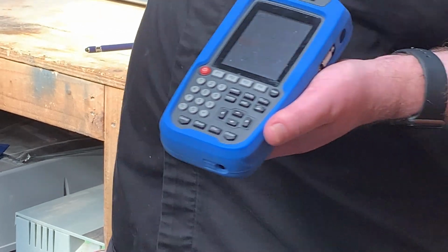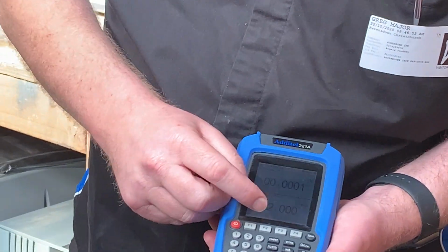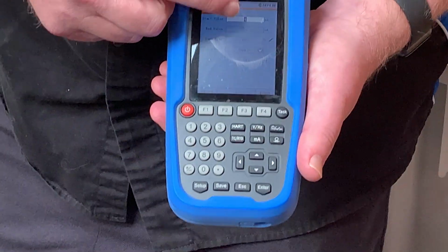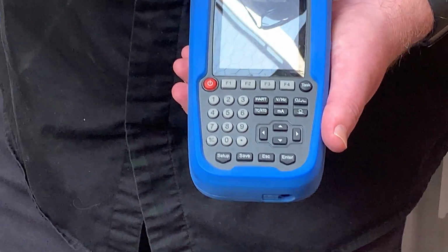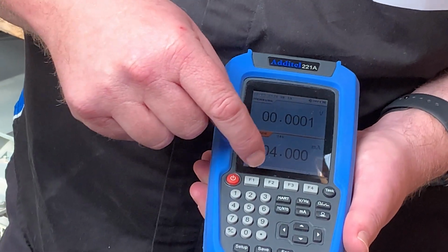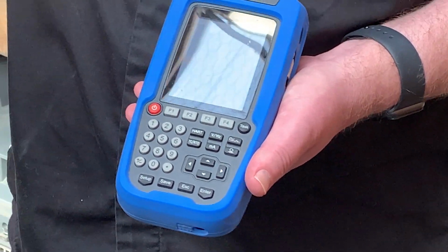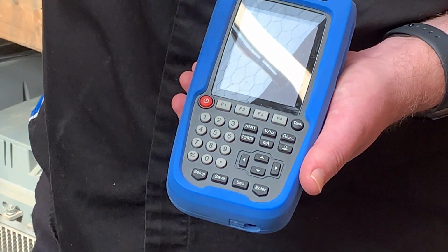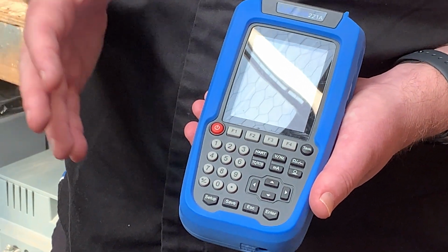So again, just be aware of what the process is actually going to do, what you tell it to do. Yeah. But you could say, ramp. Let me see your ramp between 4 and 20 milliamps over 60 seconds, and again, repeat up and down. Connect it up and start. And again, watch the valve open, watch the valve close, watch the flame rise, watch the flame fall. So it's horrendously wonderful, you know, for doing this sort of thing, for testing it out.